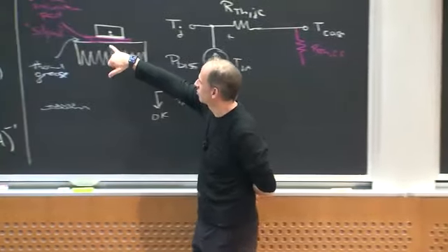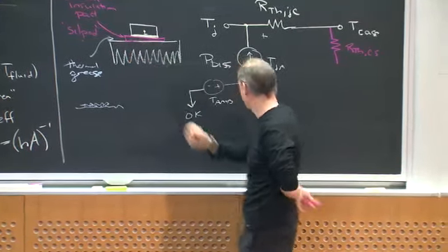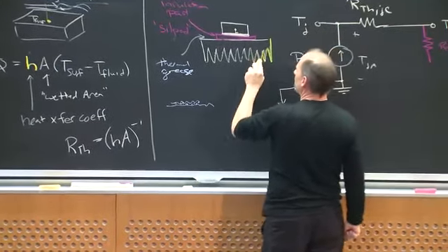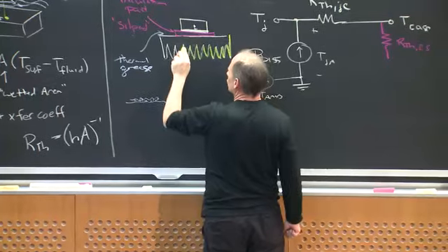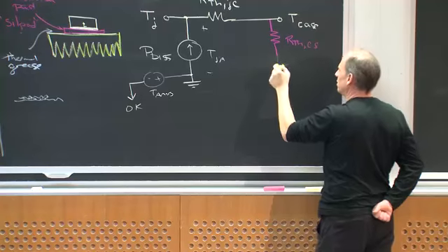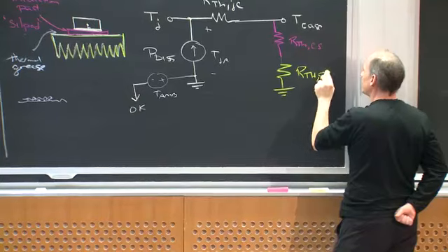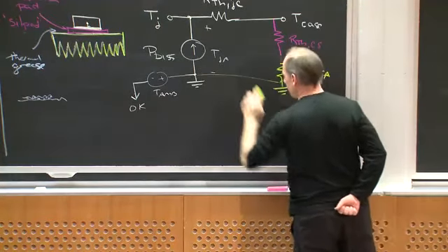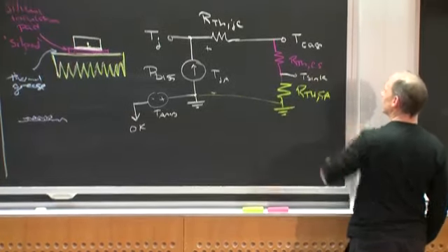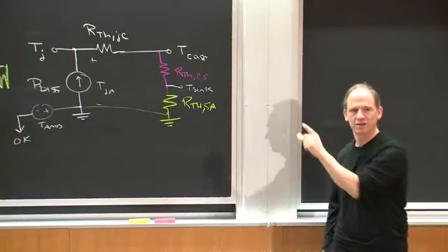That depends upon, is this grease, is it a thermal pad, what is it? And I care, because that's going to contribute to temperature rise. And then, over here I have my heat sink, right? And that heat sink, if I include what's going to transfer off it by conduction and convection, right? Maybe I say there is some RTH sink to ambient, okay? And I connect this back to ambient, and that's my thermal model, and this is T sink, right? So this is my model for the whole thing. Any questions about that? And I should say this is in thermal steady state.